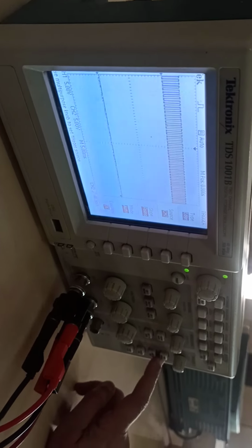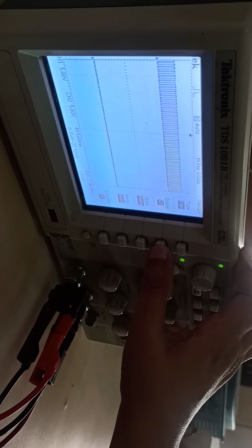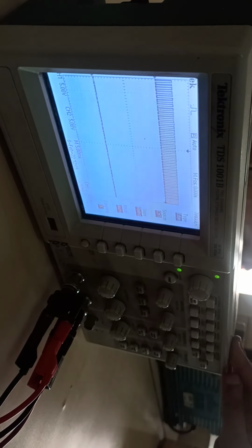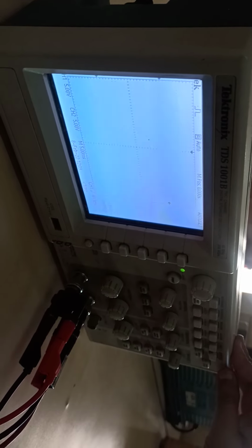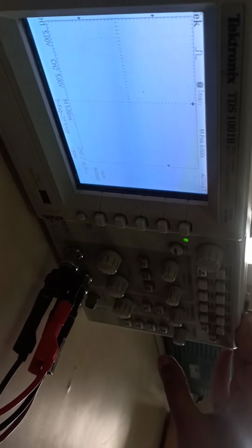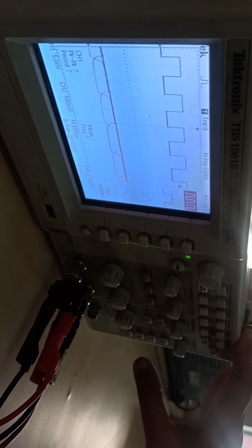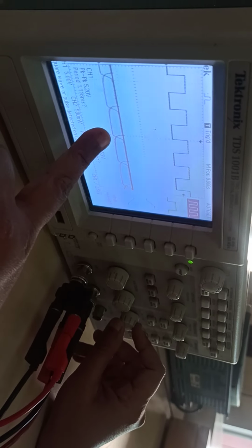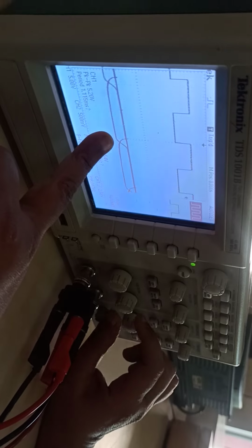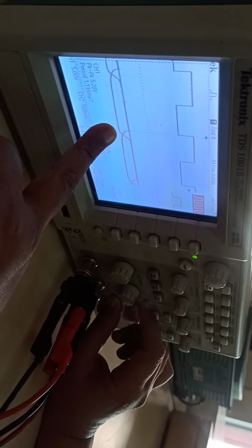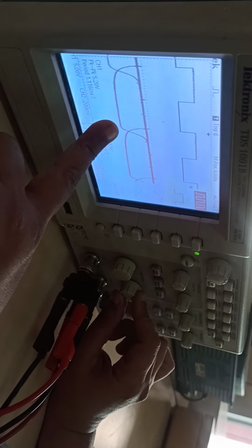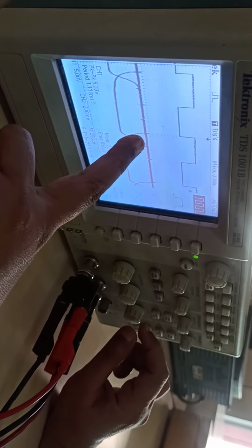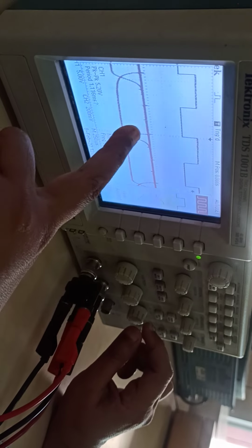So wherever the trigger source is there, you are supposed to set channel 1 as the trigger source. Then only you are able to observe the eye pattern in channel 1. Now see, we can see that this is the eye pattern where I have connected the 1 kilo ohm resistor. Now I need to find out the frequency limit. So the clock signal can be changed, where this is a wide eye open.